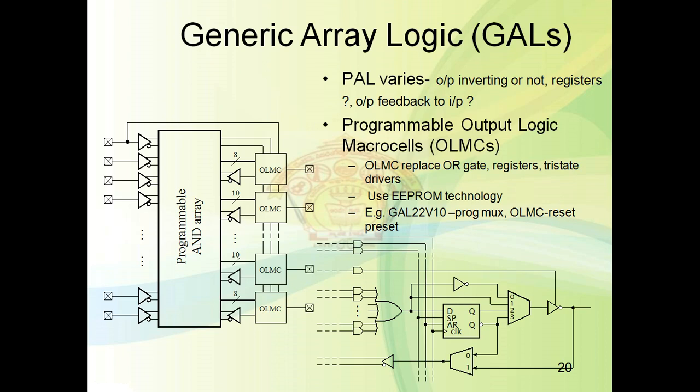Then generic array logic, GAL. In PAL, programmable array logic, some facilities are absent: inverted output or normal output, registered output or normal output, feedback output, and input-output feedback.